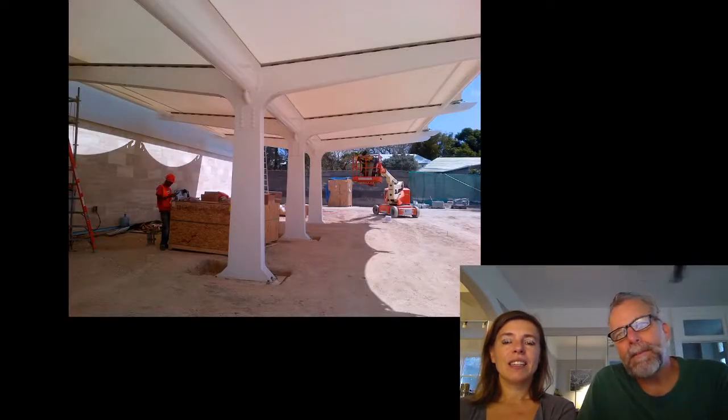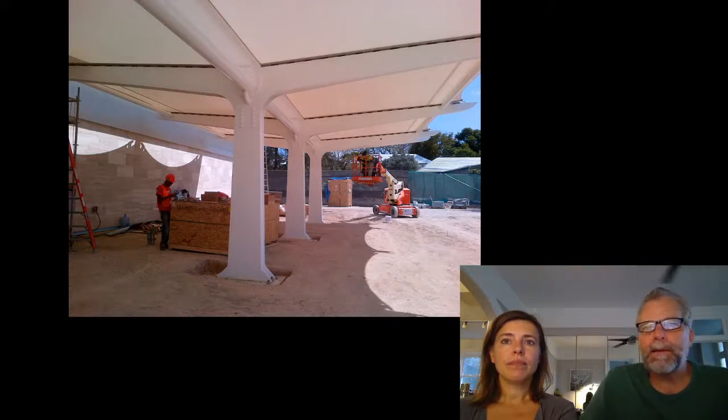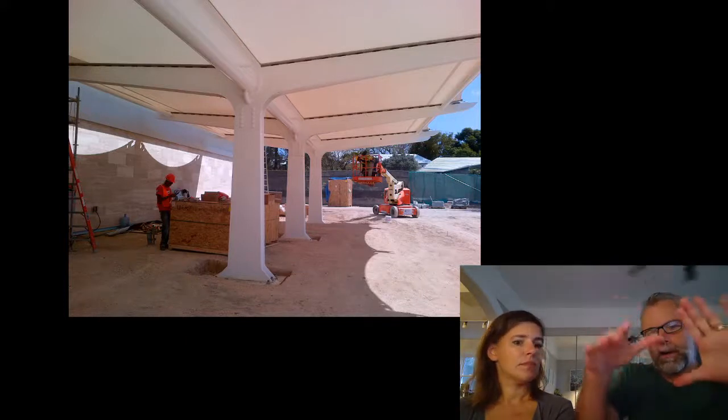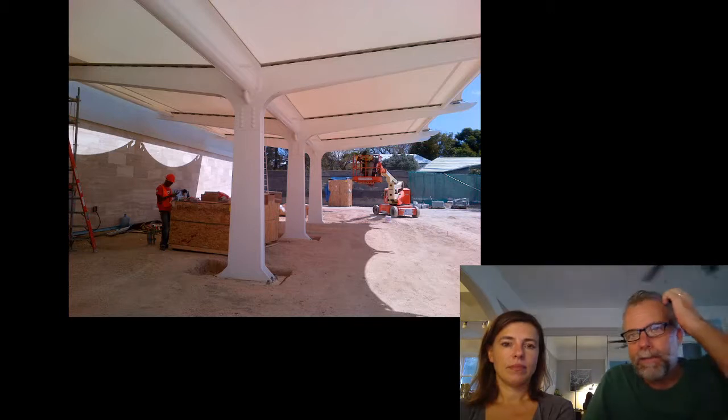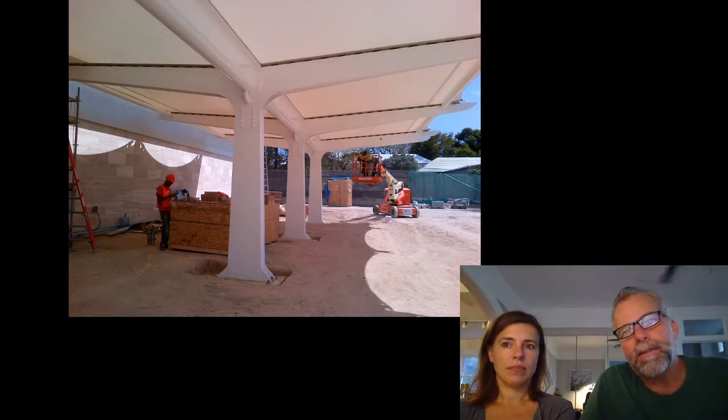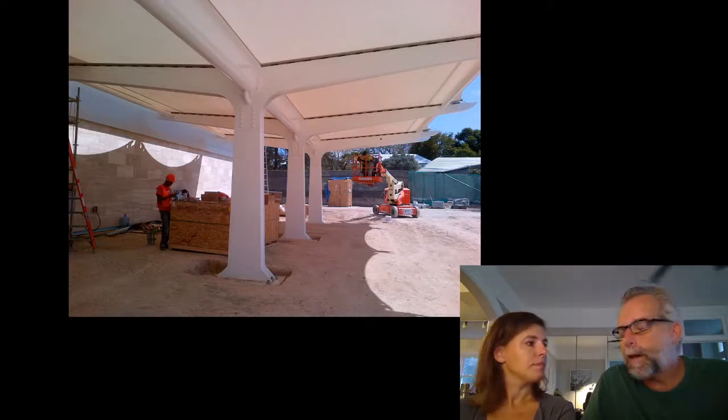So this is a fabric canopy in Bermuda. This is a flat membrane. Normally with fabric structures, you want a lot of shape in the membrane. That was inconsistent with the architectural intent, so these are perfectly flat membranes. They span just because they're so tight. It's a PTFE fabric, so fiberglass with Teflon, which makes it non-combustible, which is a big benefit.